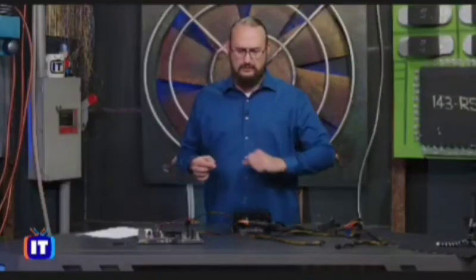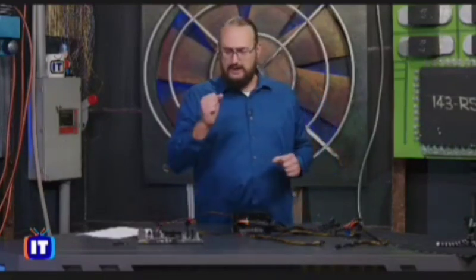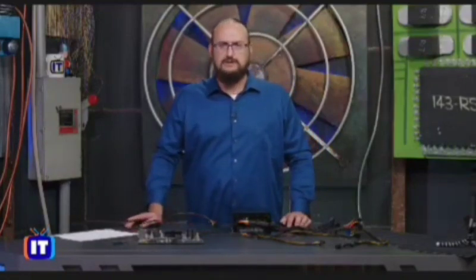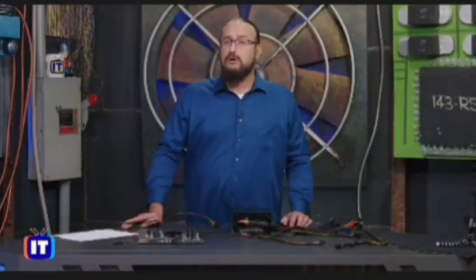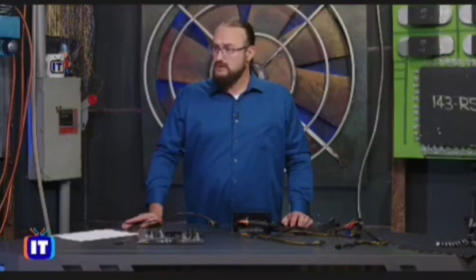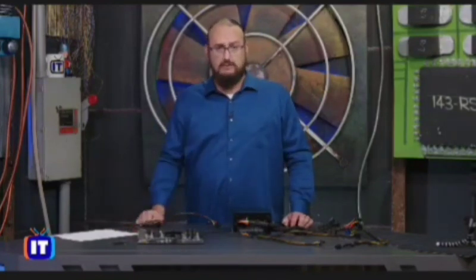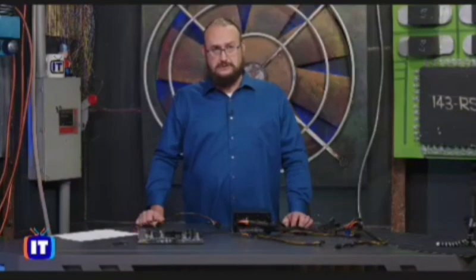It does, Ronnie, and I tell you, you mentioned that. I've actually experienced that because I took all the wattage requirements, right, and said, okay, the motherboard requires this amount of wattage, this video card needs this amount of wattage, added all that up, and I bought a 500-watt power supply, and I thought, yeah, that's going to be good for what I needed, until I brought up a video software that really demanded the performance of that video card, and it did exactly what Ronnie said: froze, crashed, rebooted.